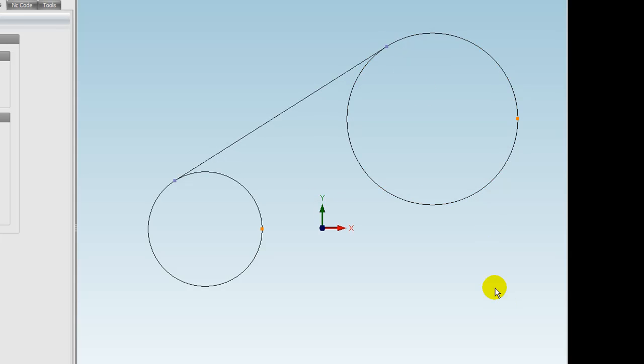So that's the tangent. And I want to move near here, but still on the outside. So left click, yeah. And then there's a tangent point there. And if I want it on the centre, then bias it towards the middle, and you can see the centre of the circle has got a snap marker there. But I want the tangent point, so there it is. So left click, and that's a simple way of drawing tangent lines.